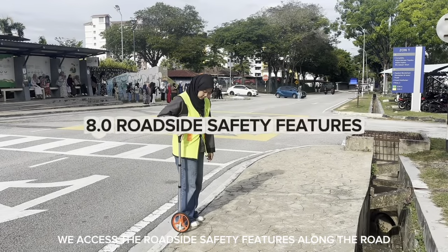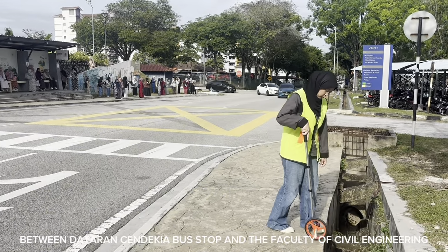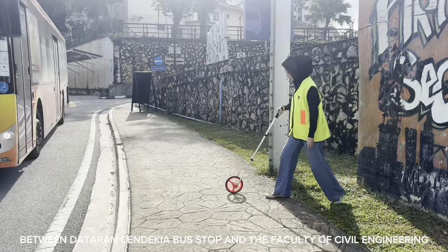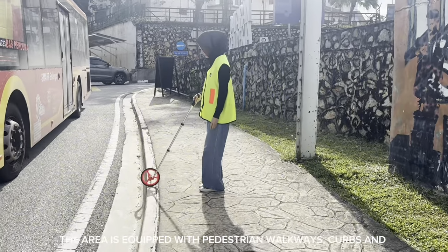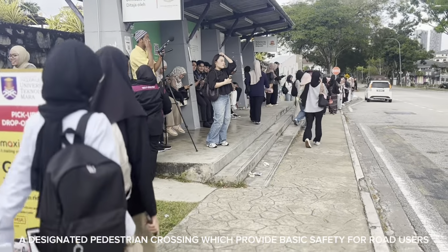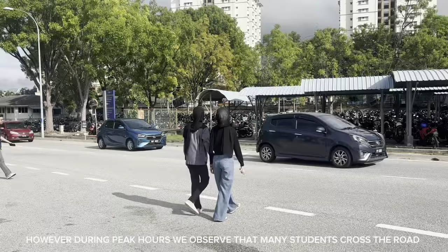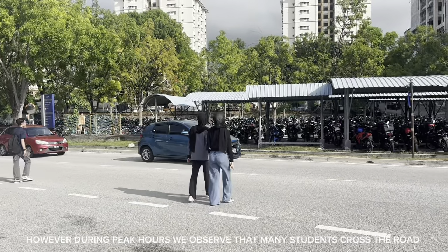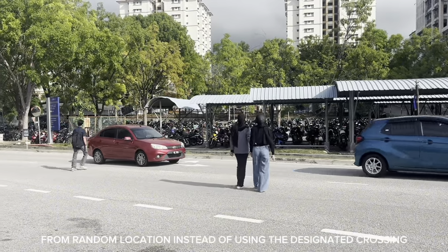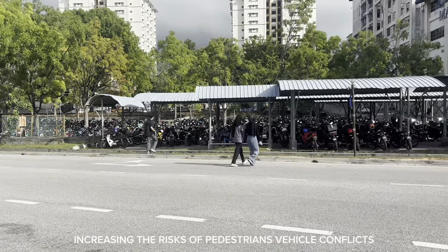We assess the roadside safety features along the road between Dataran Cendekia bus stop and the Faculty of Civil Engineering. The area is equipped with pedestrian walkways, curbs and a designated pedestrian crossing, which provide basic safety for road users. However, during peak hours, we observe that many students cross the road from random locations instead of using the designated crossing, increasing the risk of pedestrian-vehicle conflicts.